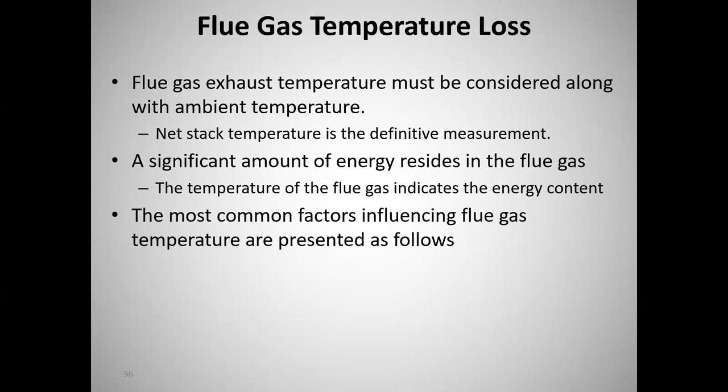But the definitive measure is the net stack temperature. That is the difference between the flue gas exhaust temperature and the input air temperature. So you have to do that subtraction. Then you take that net temperature and go to your tables to look it up. And then, of course, your boiler temperature is typically measured at the exit of your last heat exchanger.